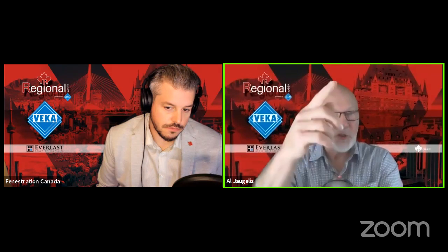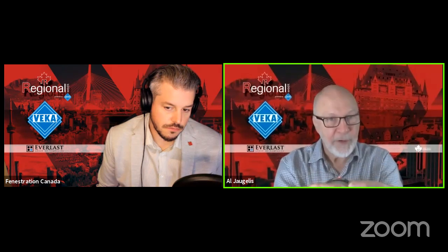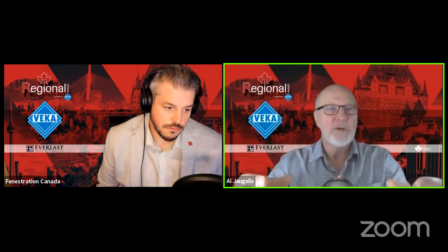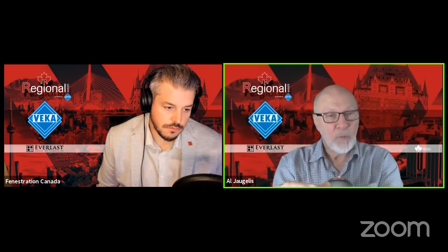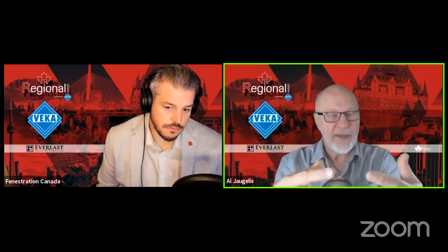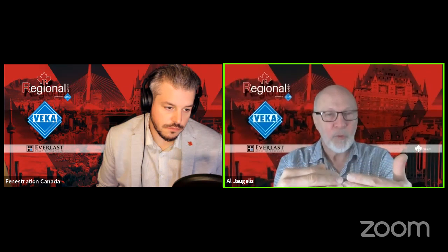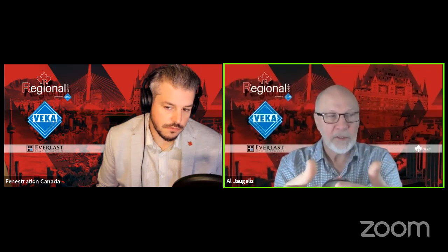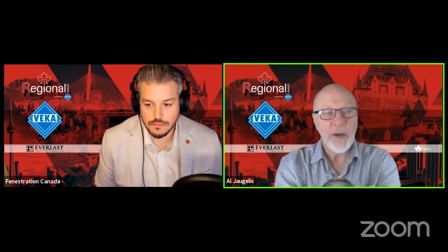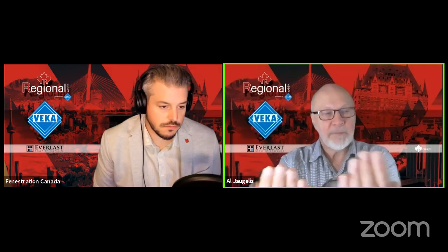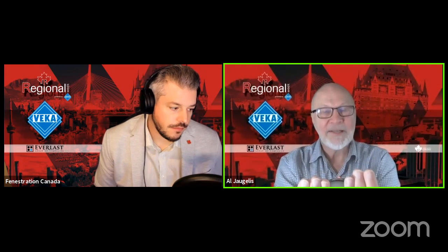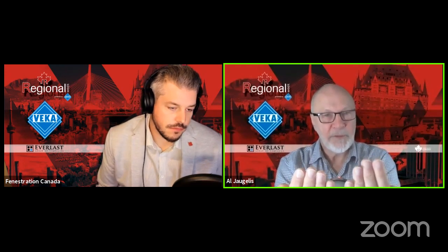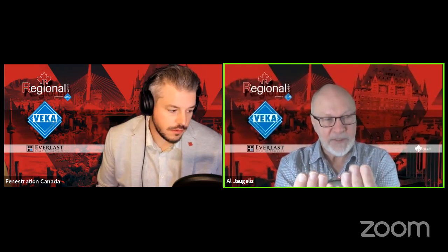You also want to make sure that the structural capacity of the 2 frames joined together, or maybe you're assembling 4 windows together, 2 above and 2 below. Well, you want to know that where all those frames join together, if they're not properly connected to one another, they're not going to resist the wind load. So the individual performance of the individual windows might be quite high. When you start assembling them together in a combination assembly, the individual performance ratings are worthless. They do not qualify the combination assembly.